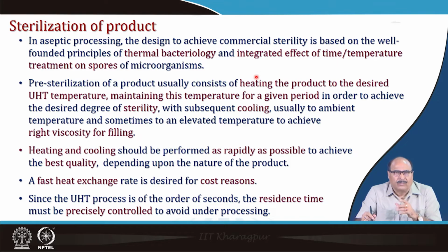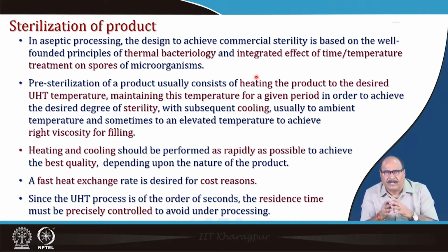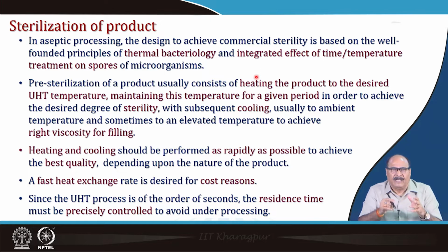Okay. So, sterilization of a product usually consists of heating the product to the desired UHT temperature, maintaining the temperature for a given period in order to achieve the desired degree of sterility, and with subsequent cooling, usually to ambient temperature and sometimes to an elevated temperature, as the case may be, to achieve the right viscosity for filling, because that is very important for concentrates etc. So, sometimes the heating is arranged to get the proper viscosity, so that the material can be properly pumped or conveyed to the filling line.